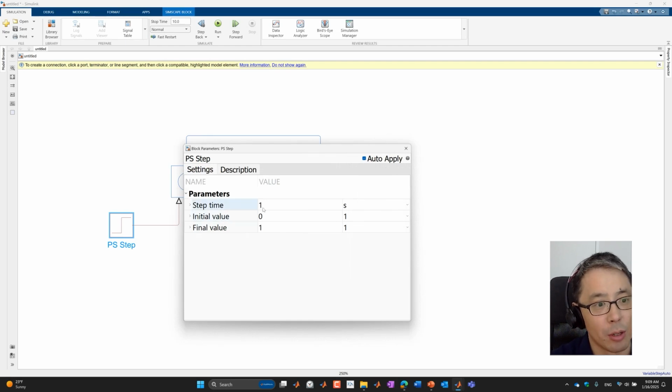So here, you can see step time. Well, let's do 400 seconds. So we will turn off the current at 400 seconds, and the initial value, we'll do minus 27, and then the unit is amps, meaning within the initial 400 seconds, we are going to discharge the battery cell with a 27 amp current.